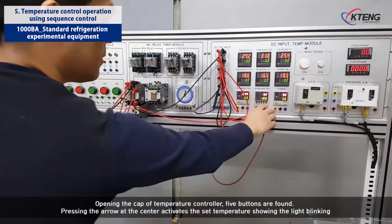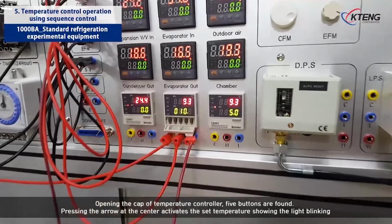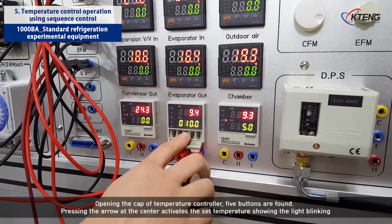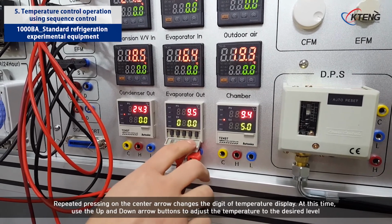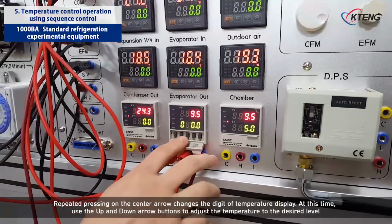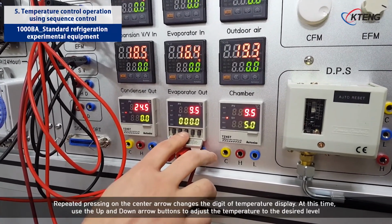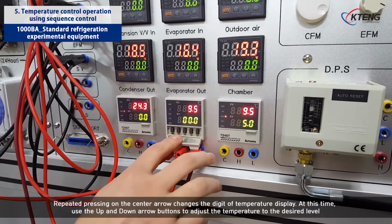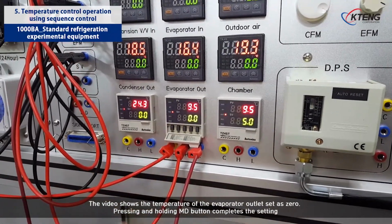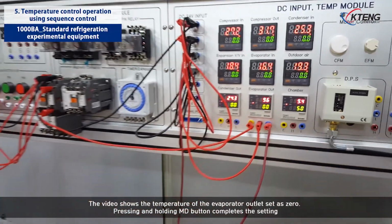Opening the cap of temperature controller, 5 buttons are found. Pressing the arrow at the center activates the set temperatures showing the light blinking. Repeated pressing on the center arrow changes the digit of temperature display. At this time, use the up and down arrow buttons to adjust the temperature to the desired level. The video shows the temperature of the evaporator outlet set as 0. Pressing and holding MD button completes the setting.